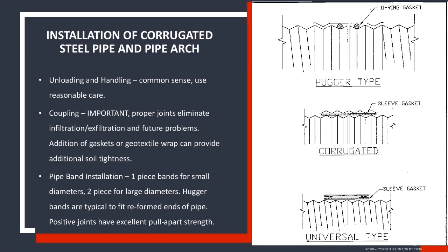So here, before we get into the actual backfill operations, let's talk about some pretty common sense things that go with installation of the pipe. With unloading and handling, it's straightforward. You don't want to dump the pipe off the truck. You don't want to be dragging it across the job site. Just use common sense and reasonable care. That way you're not beating the pipe up before it even gets into the trench.